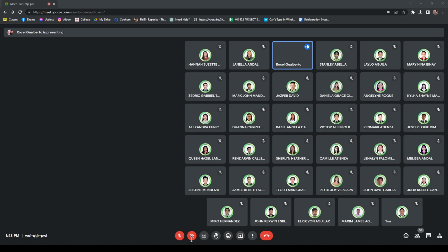Okay? Now, what if naman po, we have a thick-walled vessel? Okay? So, for a thick-walled vessel, this time, the limiting criteria T over D sub I is greater than 0.1. Okay? So, it would be a thick wall naman. Okay? So, kapag thick wall, sabi ko nga po kanina, yung stress po niya, doon sa inside wall at yung outside wall, malaki yung pinagkaiba. Okay? And mas mataas po yung nandoon sa directly in contact with the pressurized fluid. Okay? So, how do you design this kind of vessel?